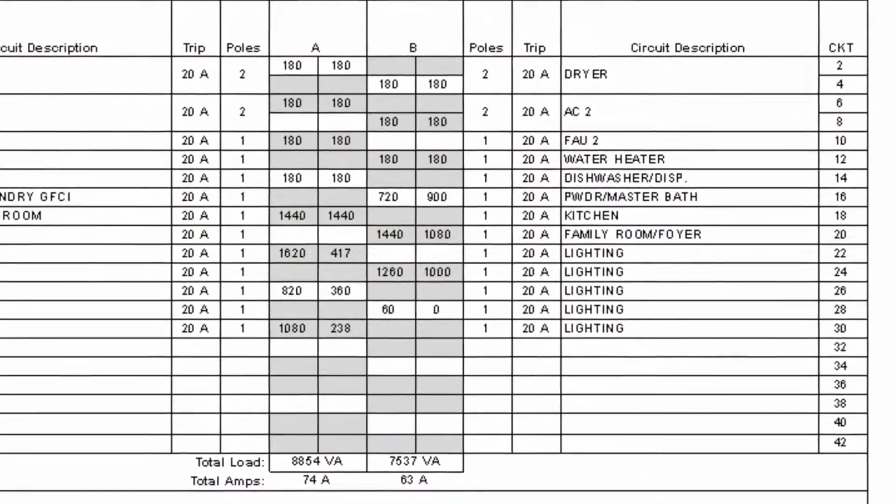I've created a collection of electrical families that are completely 2D line based. There's no model geometry in the families whatsoever, and there is a connector in there so you can connect them to your electrical panel so that you can create a panel schedule.